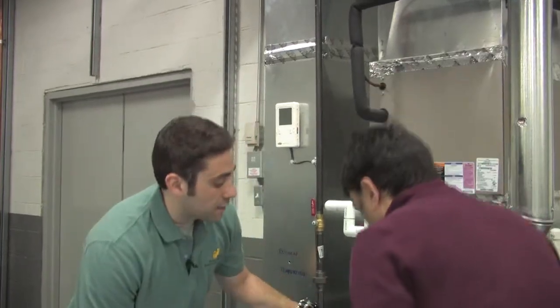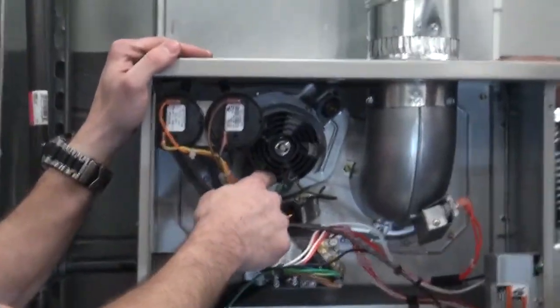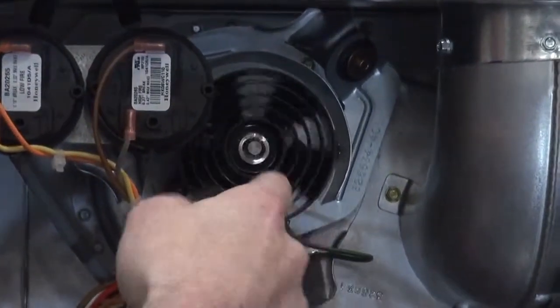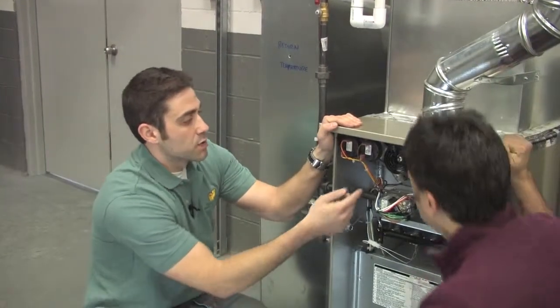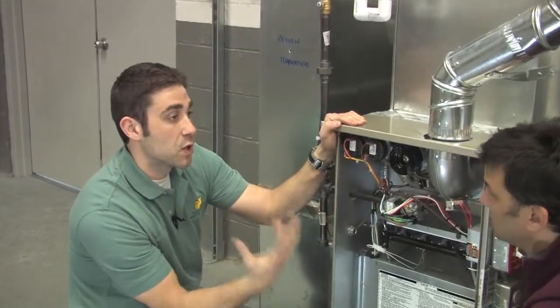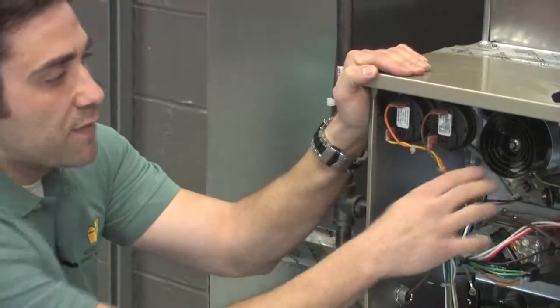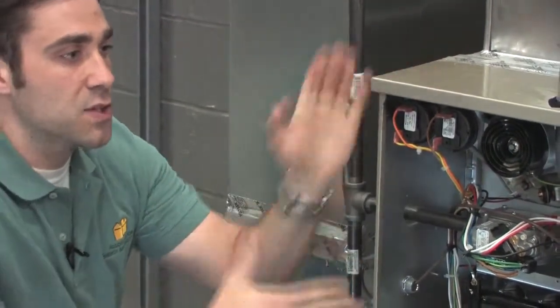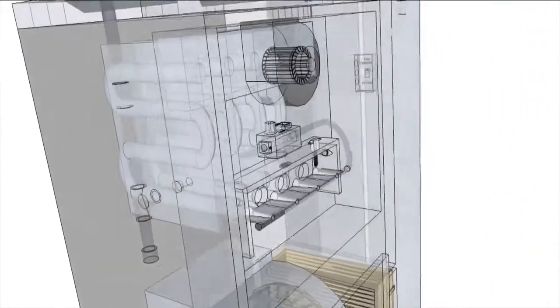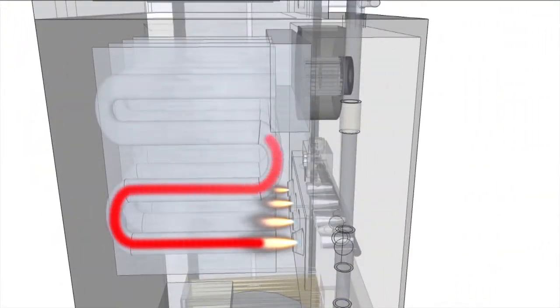So this furnace is category 1, the venting category. So it's considered negative pressure in the flue pipe and it's non-condensing. The thing that's a little different about this one is that it's induced draft. Inside the outlet of the heat exchanger, we have this little inducer motor. So it's a mechanical assist? It's a fan assisted, right. It's a draft assisted motor. So when the system starts up and there's a call for heat, this motor kicks on and starts to pull negative pressure inside the heat exchanger. Now, the reason we have this motor in here is that the heat exchanger design, instead of being just straight up, is more of a serpentine S shape. And this way we get more heat transfer, so we'll increase our efficiency, let's say from a low or mid 70s to the mid 80s.